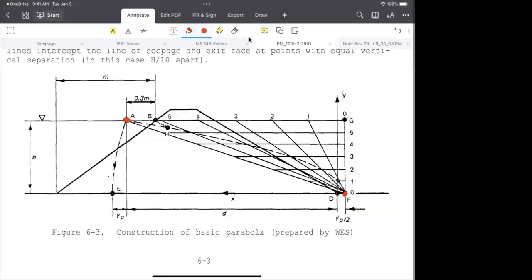So how do we draw the arc from A to E? The center is D. For that one, the center is D. We can find the point E from the distance AD. So you have a radius of AD, and you just draw an arc with this radius.